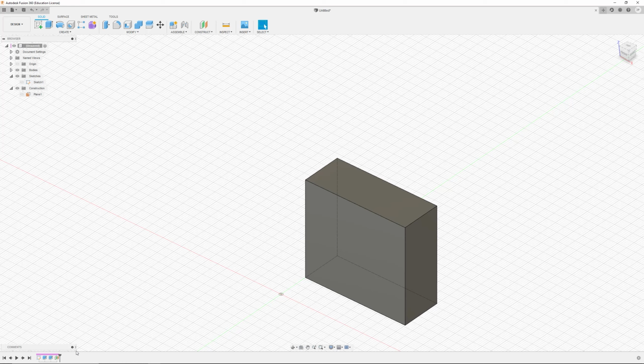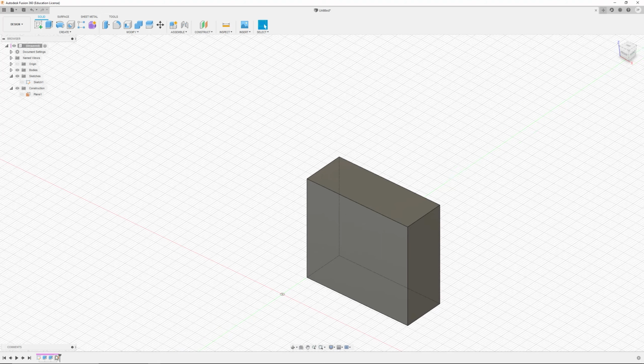No, I'm not talking about time travel, but could be. In this case, it actually does work like that in the sense that if you adjust this, in the future, this one is going to be cutting a certain amount of distance, and if you make the sketch smaller than this cut, then it'll cut through the entire thing. So we will be talking later about how to combat this kind of stuff and create quote-unquote time traveler proof geometry. Well, I should patent that. That's a great idea there.